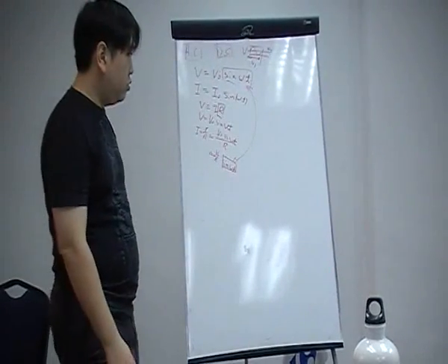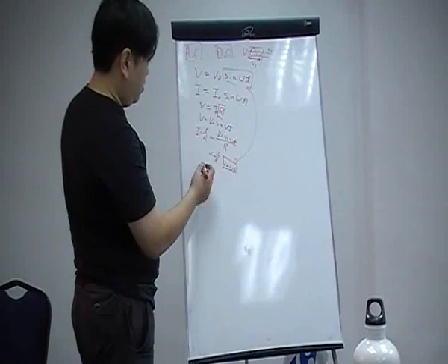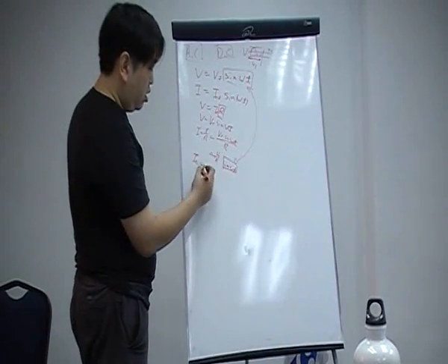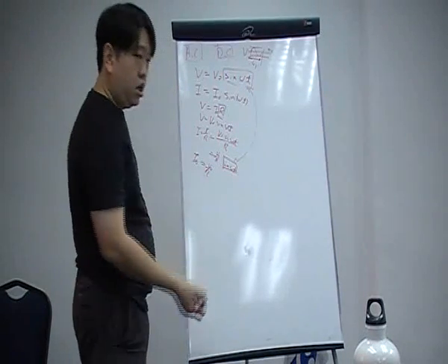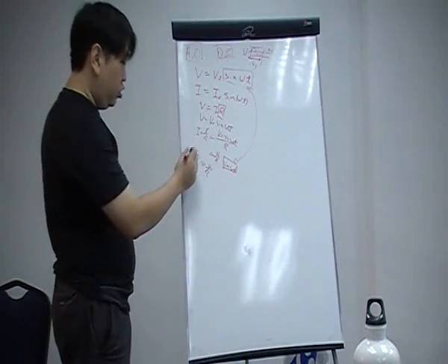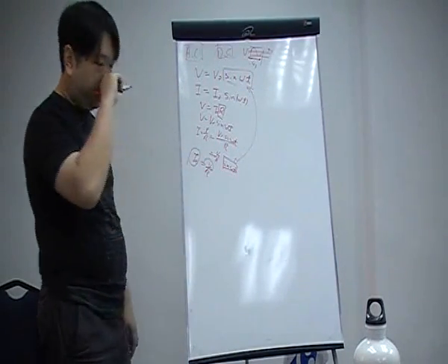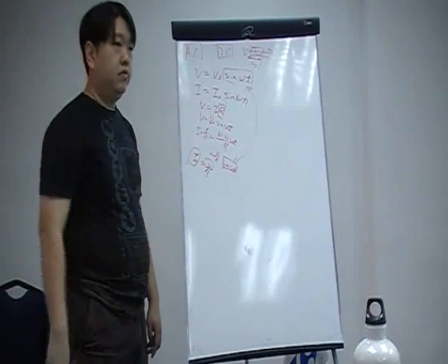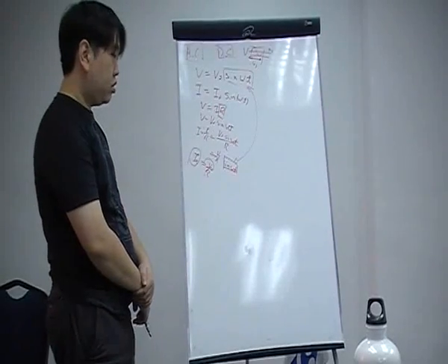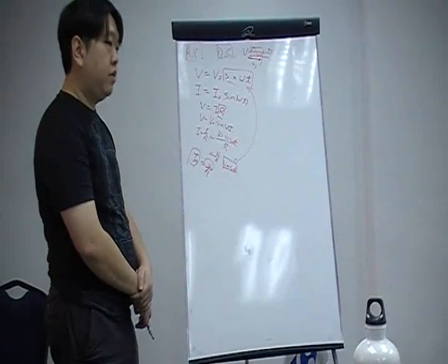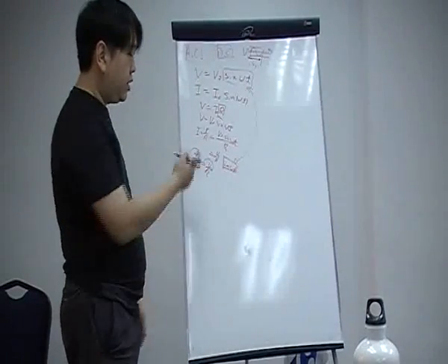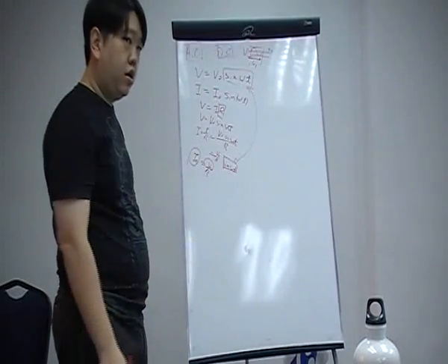Secondly, of course, if you want to talk about I naught from this equation, I naught is equal to V naught over R. So when voltage increases, current increases. When voltage is at 70% of its highest point, the current is also at 70% of its highest point. They're the same phase. And the value you can just deduce: you want the max of I, you just get the max of V over R.